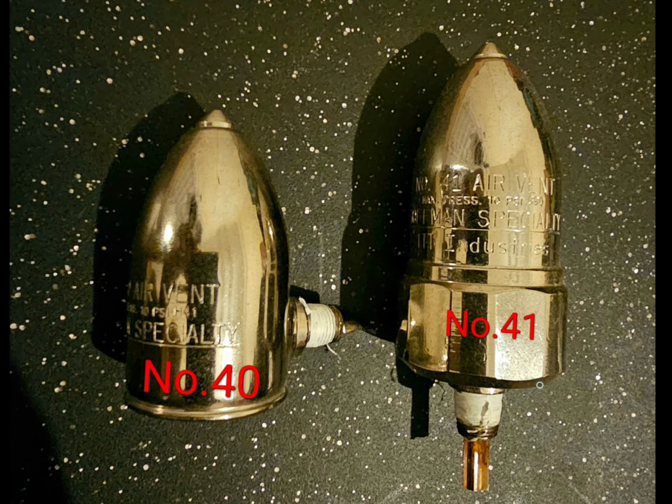The Hoffman number 41. These are perfect for steel convectors. In certain cases, you might see these slapped on top of risers, which, depending on what's taking place with that riser, I don't recommend. I would recommend a Gordon's vent. If it's an isolated riser, I would say don't use this at all. If the riser has radiators attached to it for the entire run or the entire height of the building, then you might be able to get away with this.